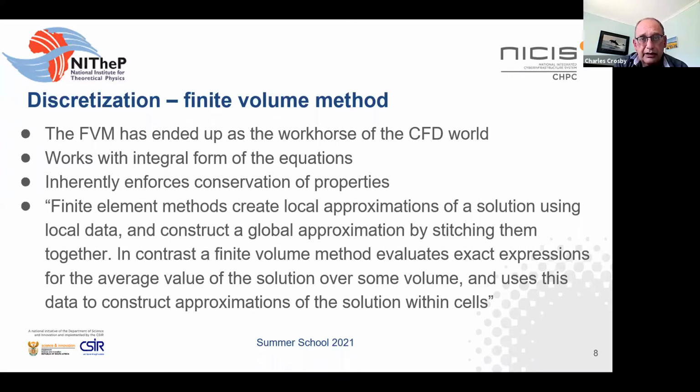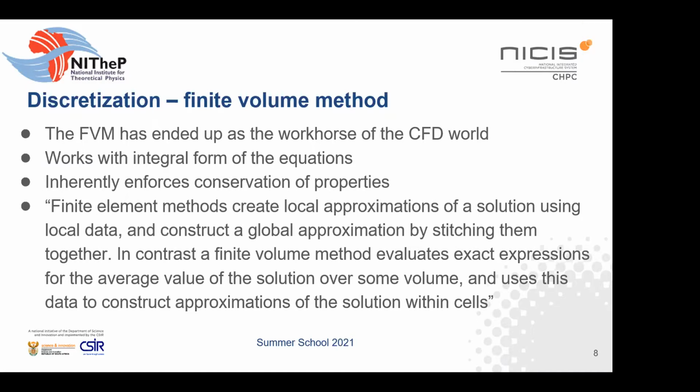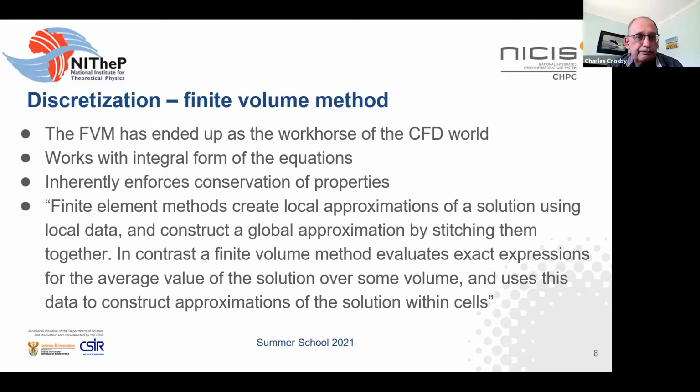There are hybrid schemes where you can blend a certain amount of first order and second order. And sometimes if you get very nasty kinds of equations where you've got something that simply will not settle down in second order accuracy, it's worth blending in a certain percentage, 20%, 30%, first order upwind differencing to stabilize it.